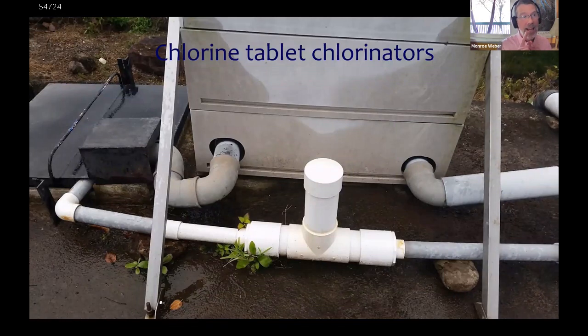So on the back side of this was another chlorine feed system. The cap of that T is meant to be removable, although I tried and couldn't. And what you do is you drop a chlorine tablet, like a hockey puck of chlorine, that you would drop in that T, and you might drop several of them in there. And then some of the water is flowing past that T and dissolving that chlorine tablet over time.